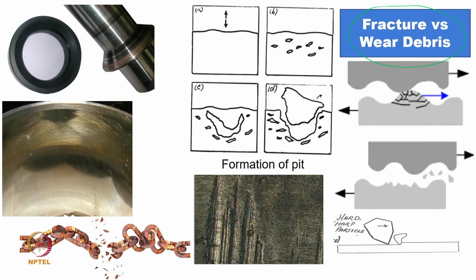We have shown these diagrams. We say there is a stainless steel shaft, there is a carbon graphite mechanical seal. When this seal is used along with the stainless steel shaft, what happens? The carbon graphite layer, a black layer, gets transferred on the surface, and this transferred surface is really reducing the coefficient of friction, but with time it also causes removal or delamination of this layer.